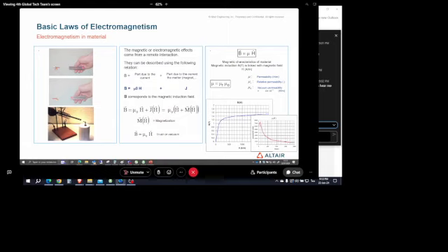Then the magnetic field creation and variation is something that we need to canalize. And this is why we use steel or a magnetic circuit on the stator and the rotor, and we are not using plastic or wood. Why? Because we need to canalize it.